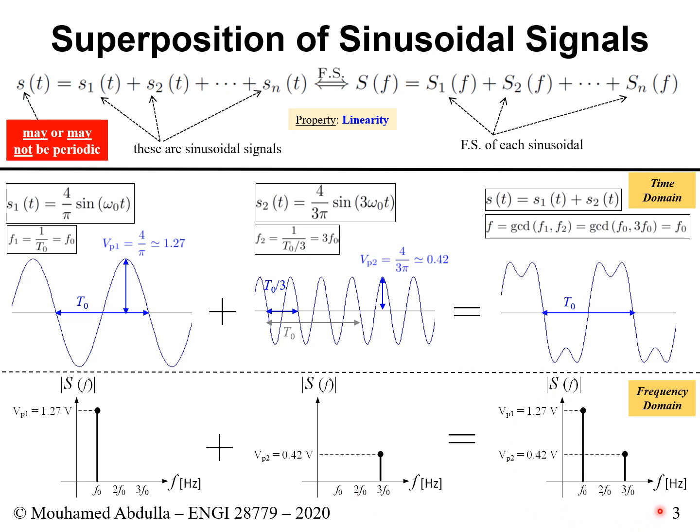Now, let's say in an evaluation, I or some other professor asks you, well, that's nice, good effort, you were able to go from time domain to frequency domain, but can you represent your result in dBm? If that's the case, the process to go from peak voltages to dBm is always the same. There are 5 steps that you have to follow. Step 1, find the peak voltage.